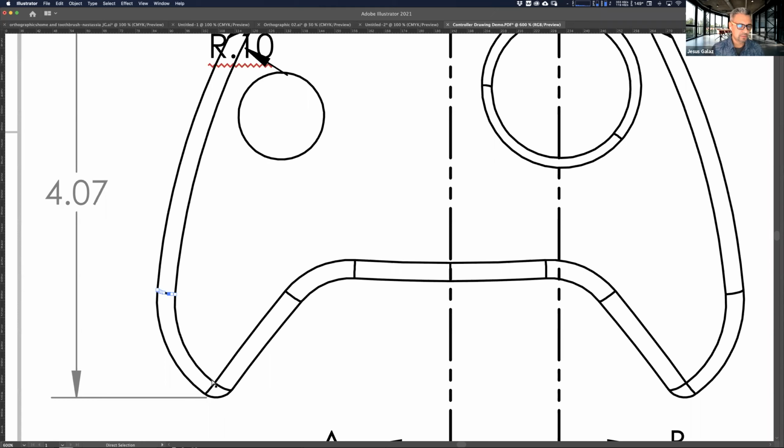You don't really need to show the way this face connects with this face, especially with a line that is the same thickness and value as the outer line. It just confuses someone that looks at this and says, okay, is there like a little gutter on the outside of this and maybe like a vertical wall or something? Is that why they're showing this? So it's one of those things that you would get rid of.